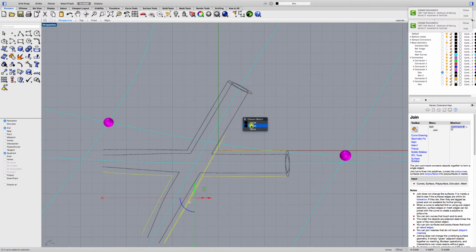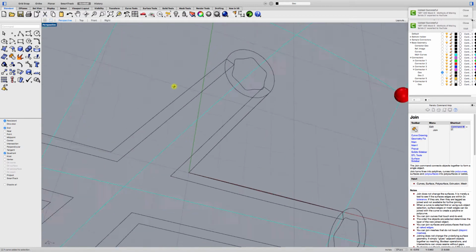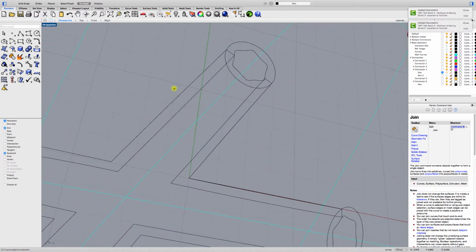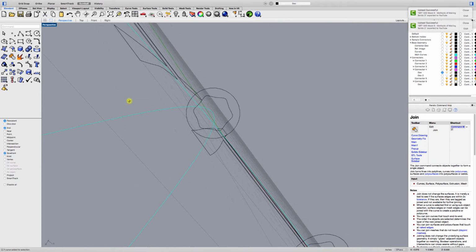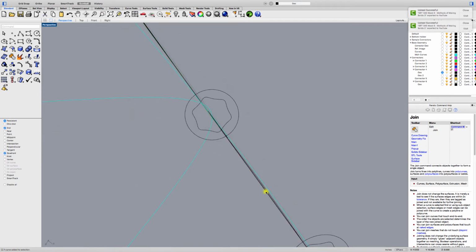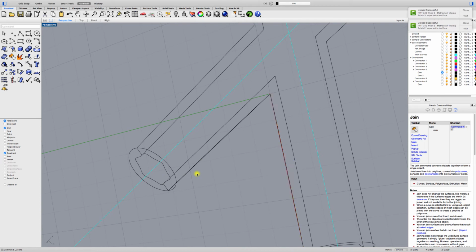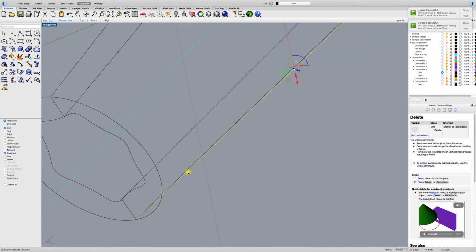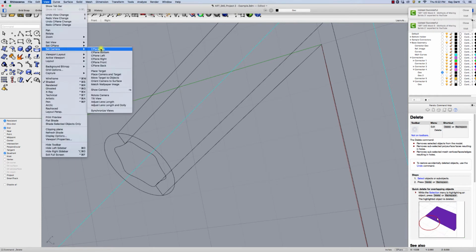oh, double curve. What's that about? Oh, the double curve is from the perspective view. If I were to move this out, that curve, you can see are the curves that are probably not planar. So I'm actually just going to delete those because I don't really care about them right now. Now what I can also do is to come back to set camera view, C-plane top.